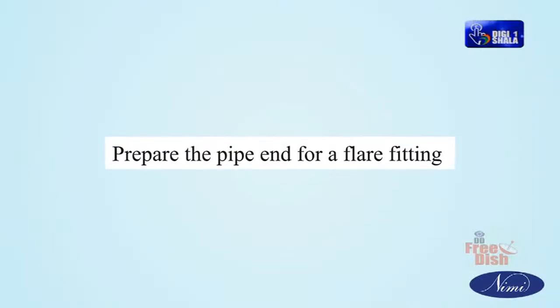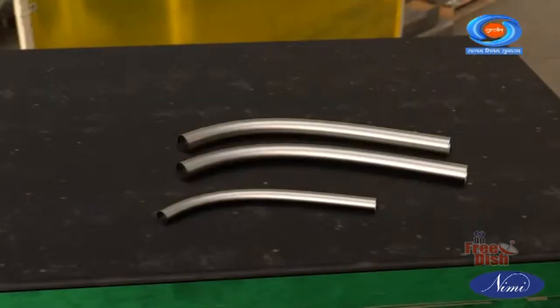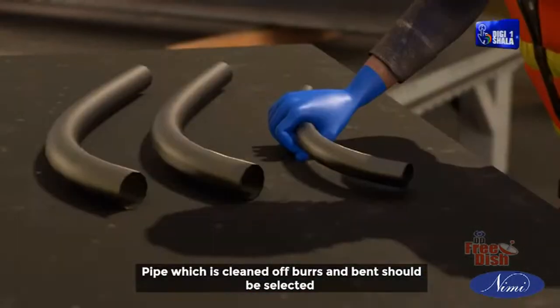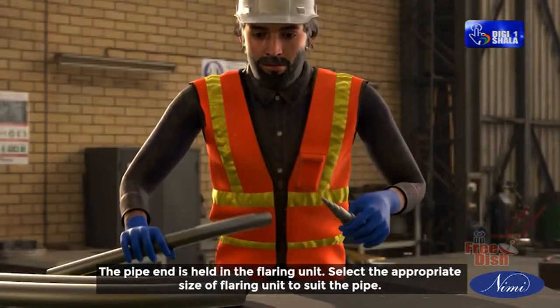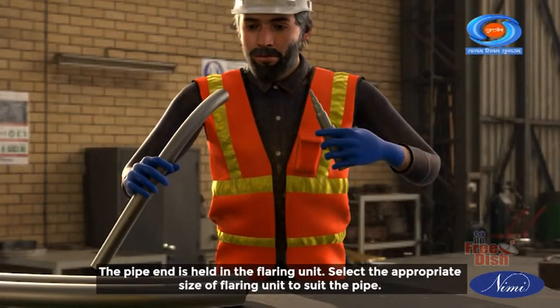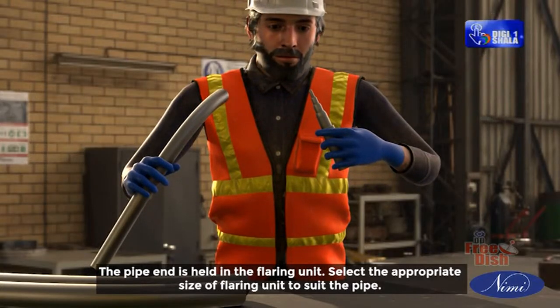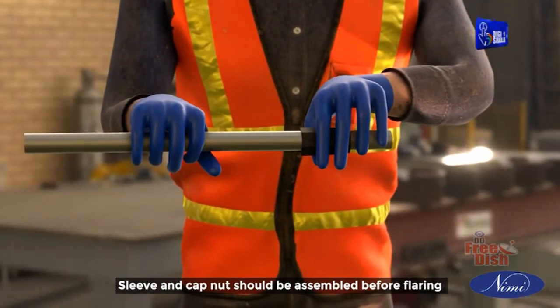Prepare the pipe end for a flare fitting. Flaring with block and punch tool. Pipe which is cleaned of burrs and bent should be selected. The pipe end is held in the flaring unit. Select the appropriate size of flaring unit to suit the pipe. Sleeve and cap nut should be assembled before flaring.